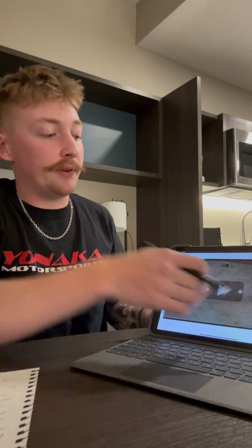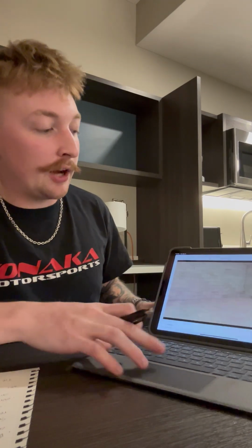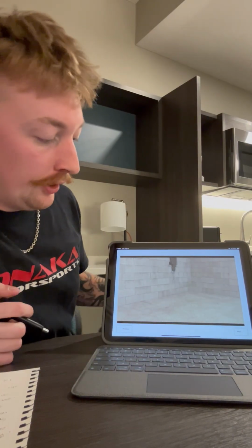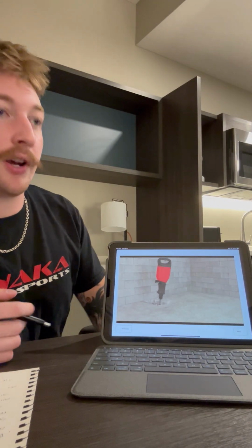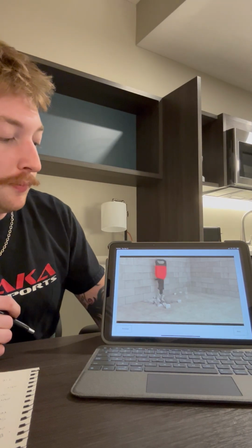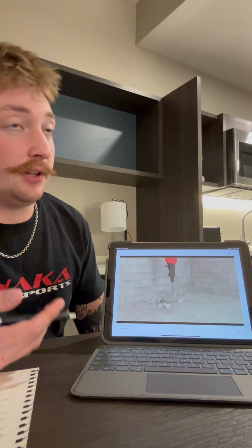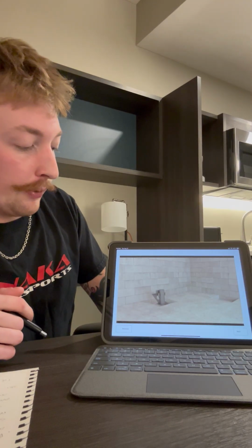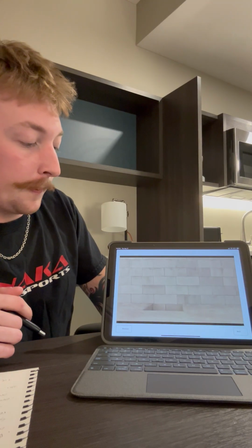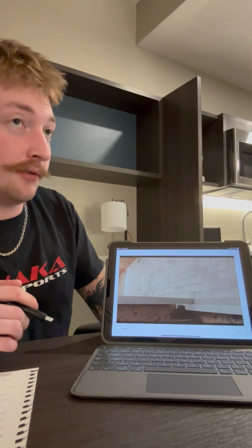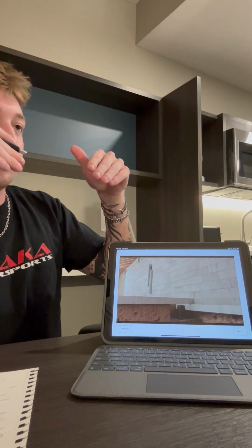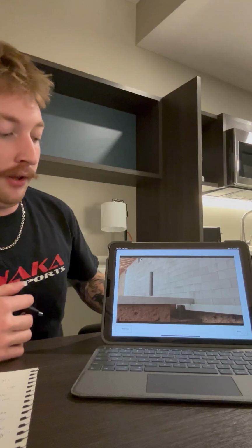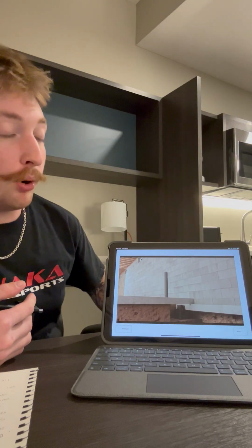This is a little bit of a better video for you, just to kind of expect what's going to go on in your basement. So first, we're going to jackhammer some of that concrete out, because obviously you're having issues with the interior mostly. They're going to attach the bracket. Actually, the bracket will be placed underneath the footing. Then we'll go ahead and install the push pier.